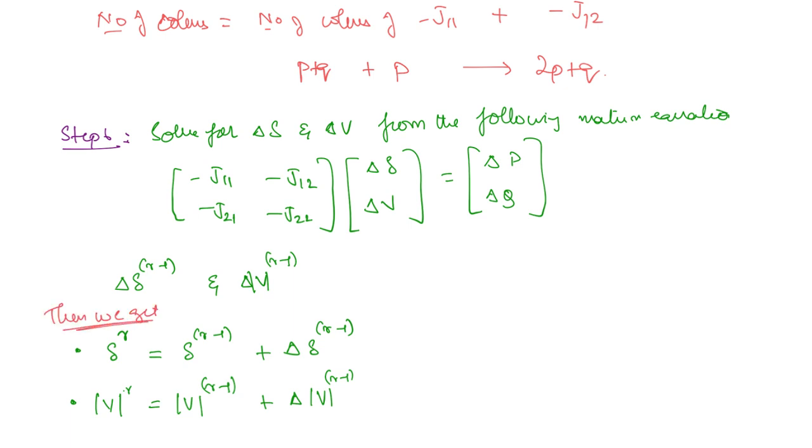Now here, sometimes for a PQ bus, the voltage limitations will be given, the minimum and the maximum allowed voltage. In that case, we have to change the calculated values accordingly.